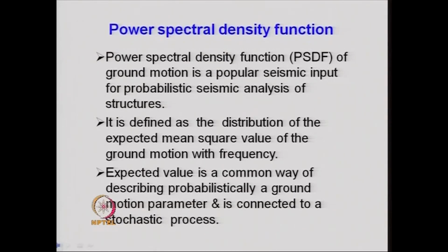Now when we perform a random vibration analysis of structures for future ground motion, that is, the ground motions are modeled as a random process, not as a deterministic process, then we require the power spectral density function.